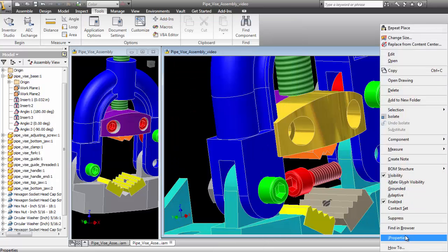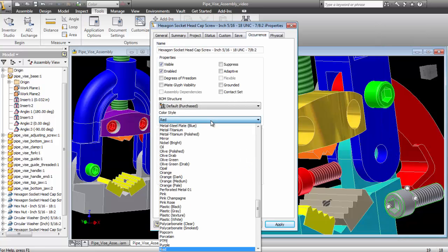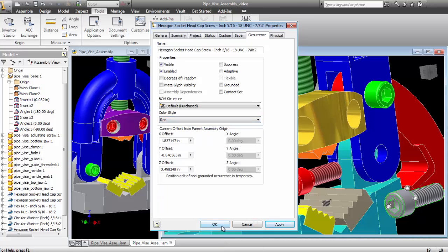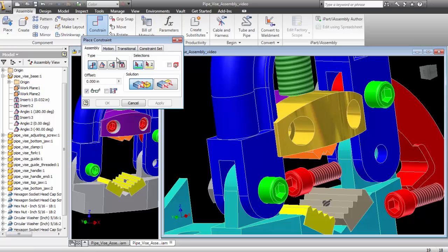And we'll go here and get this one. They wouldn't both have to be the same color necessarily. Okay, and then we'll insert them. Back to our assembly, constraint, and you have to go to insert. Mate is the default. Insert, boom, boom. And then we'll go here and get this one and that one.